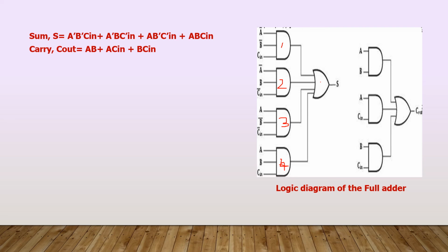And next one is carry. It consists of 3 min terms, so we'll be using 3 AND gates here. And finally, these 3 min terms are added together, so we'll be using an OR gate here. So likewise, we can represent the full adder.